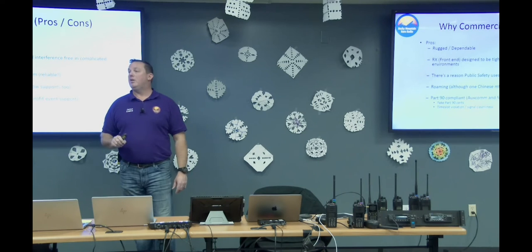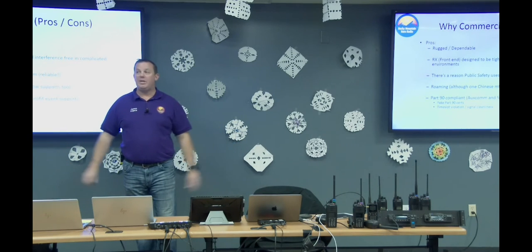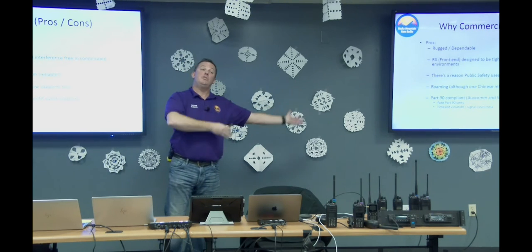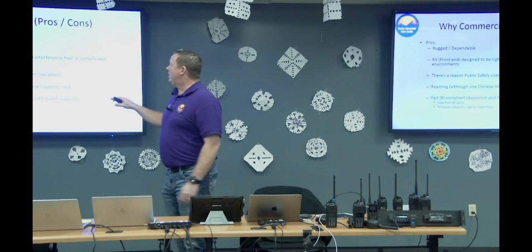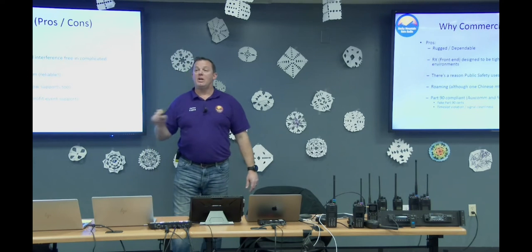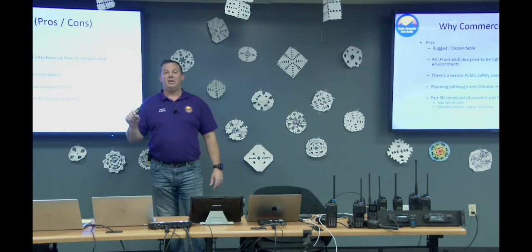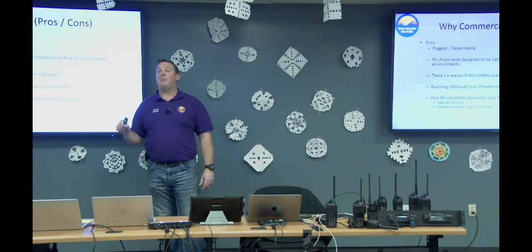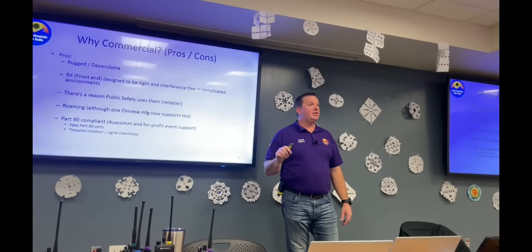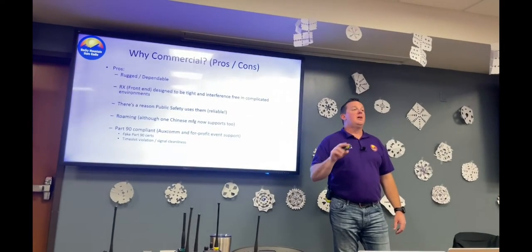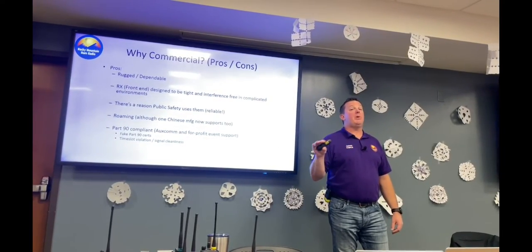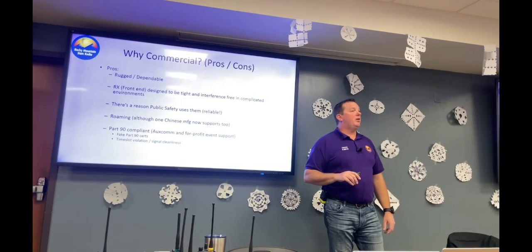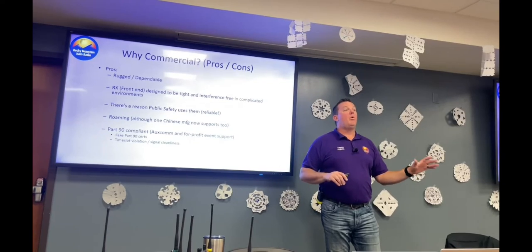If you buy a commercial radio, you are covered. They are all designed into Part 90. We just happen to use them in the ham bands. A lot of Chinese radios are saying they have Part 90 certs. Some have Part 90 certs that went through the certification process. Some just published a copy they found on the internet and said, we're certified. Some have legit Part 90 certs. And if you go take 10 of those radios and put them on a service monitor, 7 of 8 of them won't meet those certifications.